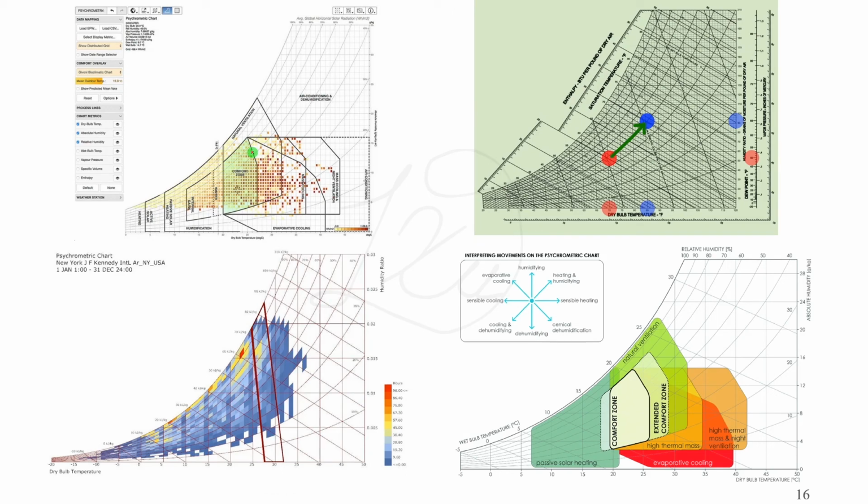Psychrometric charts may not look all the same, but the fundamental principles are all the same. You firstly need to know what pressure that chart applies to. Find where the dry bulb and wet bulb scales and lines are, and find the scale and lines for the other parameters. To sum it up, in this video we have introduced the psychrometric properties of air and the equations to calculate these properties, as well as read them off from a psychrometric chart.